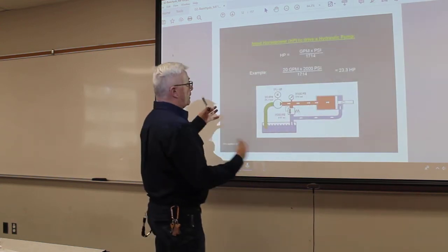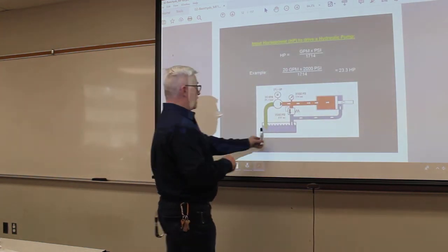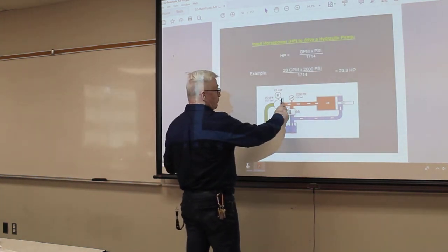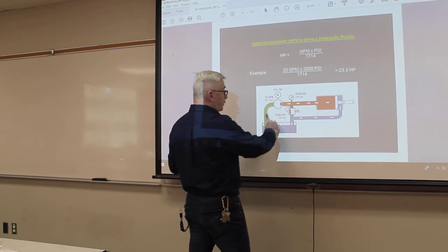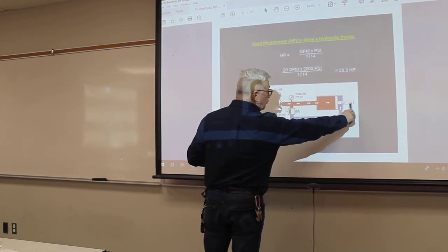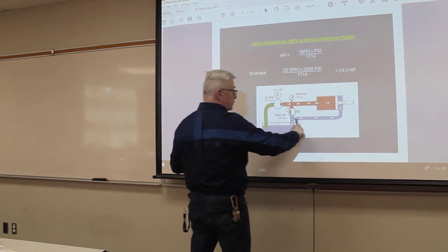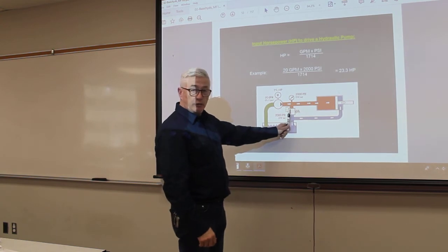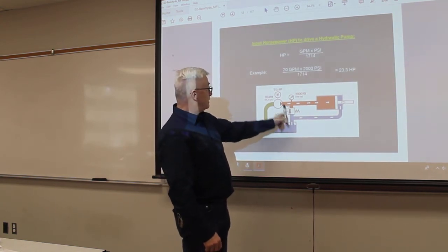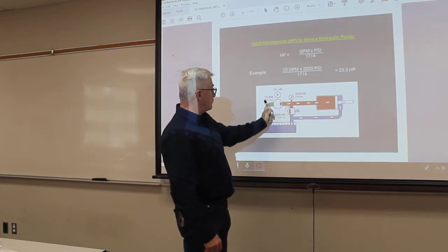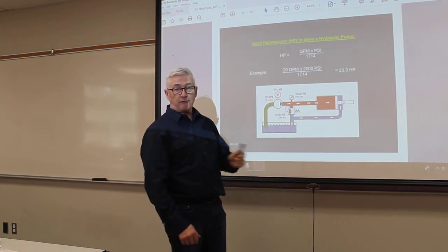All right? Now, in this one, we change the numbers up a little bit. We'll just go over the outline very quickly. We have a pump operated by an electric motor, which creates flow and fills my piston. We do some work with the piston rod, and we return the fluid back to the reservoir. My pressure regulator is set at 2,000 psi, and you can see that's what I'm reading on my gauge, and we're getting 20 gallons per minute as my flow rate.